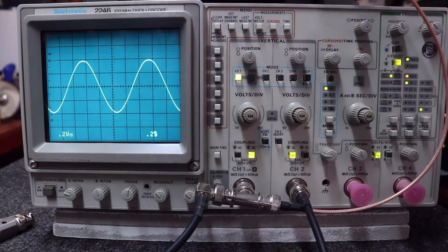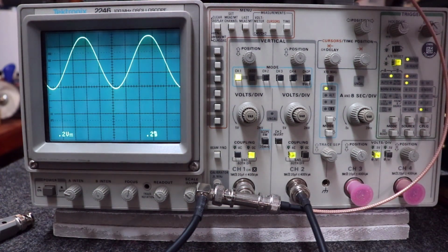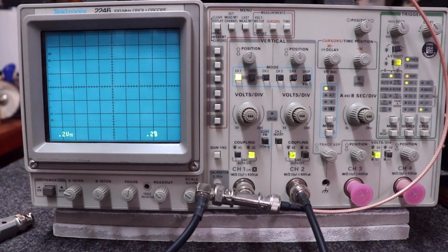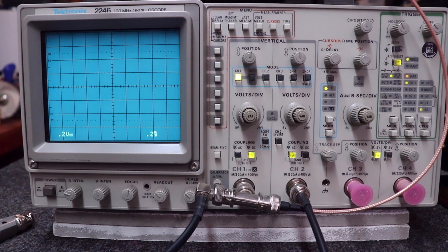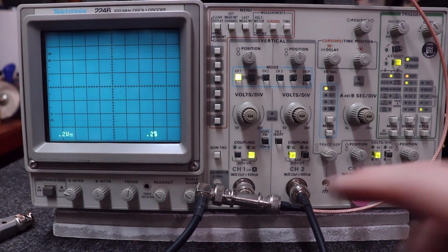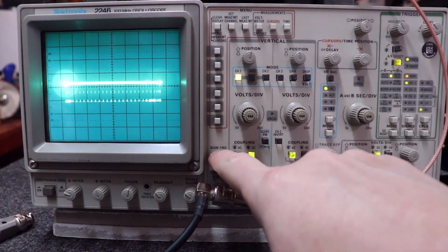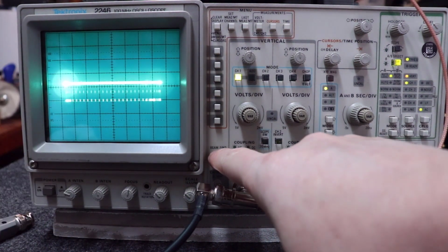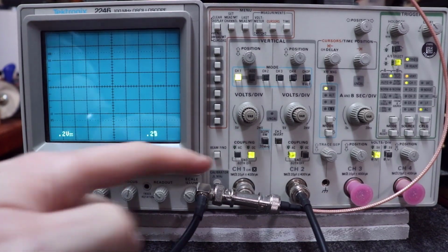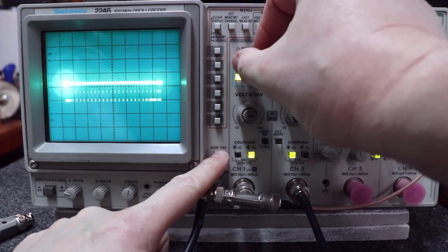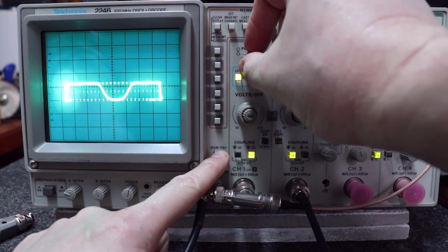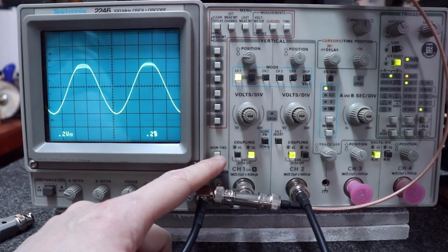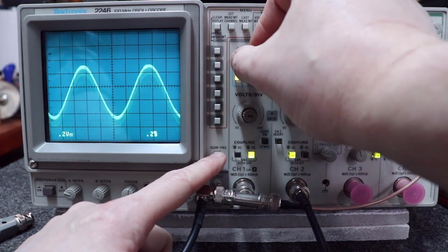I put it back on DC coupling. Let's just say you clipped on with your oscilloscope probe, and boom, you don't see anything on your screen anymore, but yet you know there's a signal there. You can use this Beam Find button, and look what it shows you. See the line at the top? It's telling you that signal is going off the screen upwards. So I can grab my position button and start scrolling it back down, and you can see it come back into focus here, and you'll see it's back online.